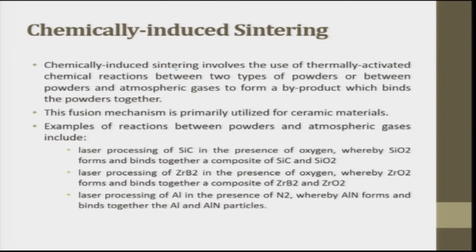Chemically induced sintering. Chemically induced sintering involves the use of thermally activated chemical reactions between two types of powder or between the powder and the atmospheric gas to form a byproduct which binds the product together. In a very simple fashion, such that you can understand: when we make laddu, we add ghee to it. The function of the ghee is to make sure that these smaller particles are held together, right.